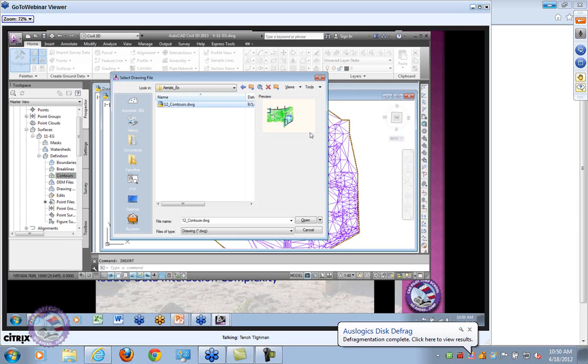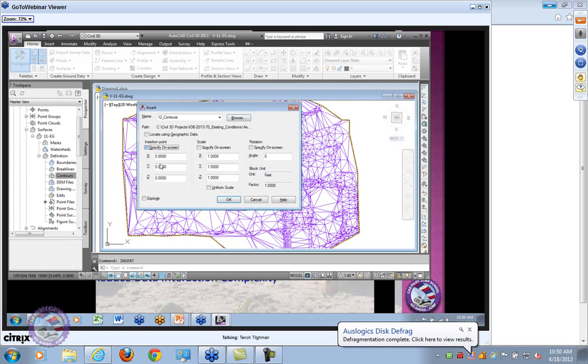There are easy ways to do that. I can do a map query and reach over inside that drawing and just pull a copy of those out. Once again, I'm going to simply use the insert, locate. It happens to be in the same coordinate system because that's what I demanded he do, and I'm going to explode it. Why am I exploding it? Because I don't want double copies, I don't want the block itself, I just want the AutoCAD crud.